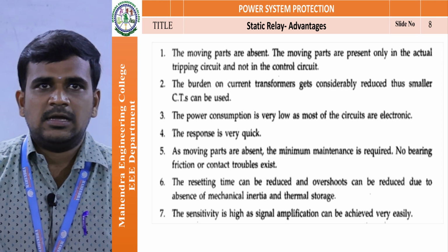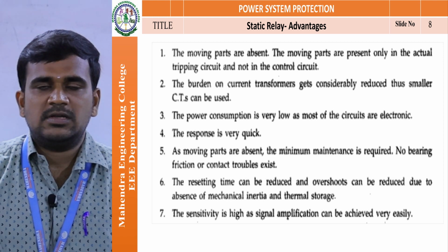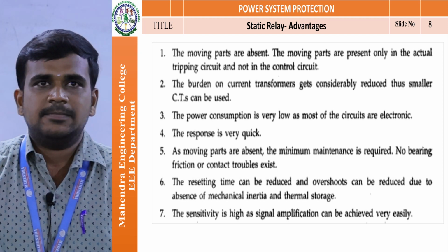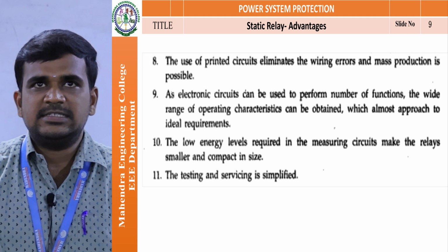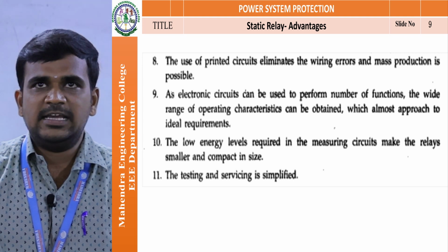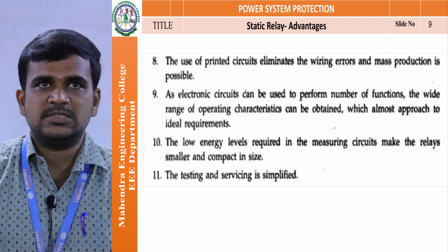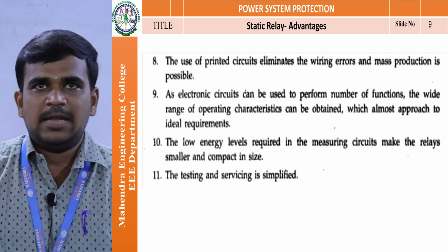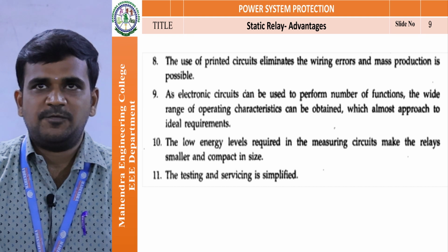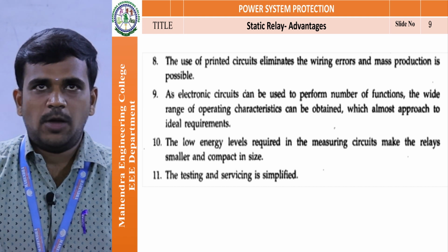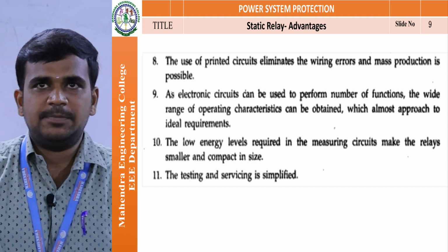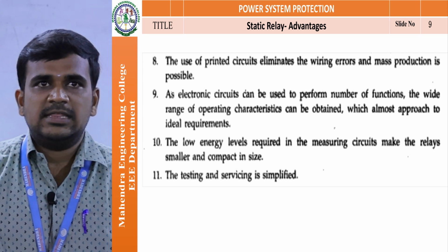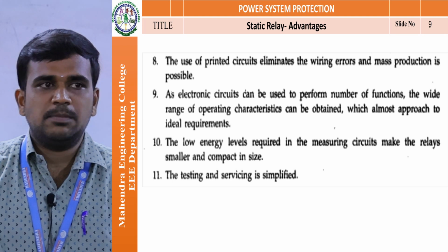The sensitivity of the static relay is high compared to the electromagnetic relay. The use of printed circuits eliminates wiring errors and mass production is possible. The last one is that electronic circuits can be used to perform a number of functions. A wide range of operating characteristics can be obtained, which almost approach the ideal requirements. And testing and servicing are simplified.